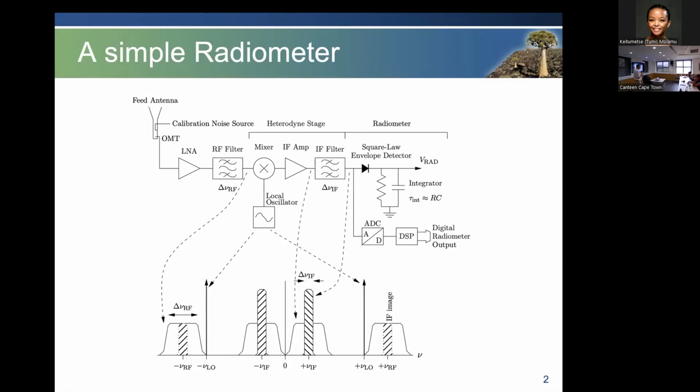And we can do that with impunity because of image rejection and Nyquist theorems and everything else. We don't lose any information if we just shift that band down to a lower band, which I sort of try to show in the bottom graphs there, by multiplying by a local oscillator. Why do we move to the lower frequencies? Everything's much easier down there.